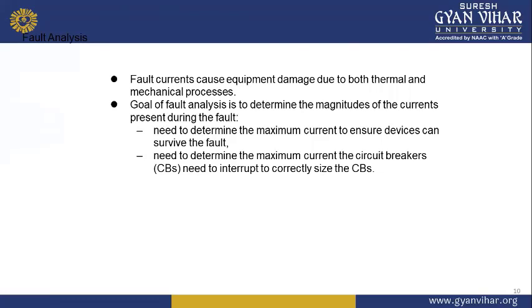Under steady state short circuit conditions, usually the armature reaction of a synchronous generator produces a demagnetizing flux. In terms of circuit, this effect is modeled as a reactance XA in series with the induced voltage.